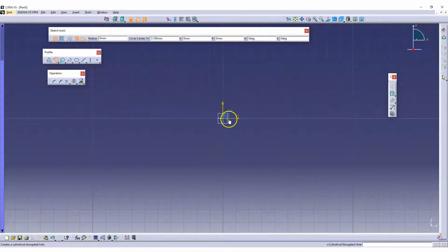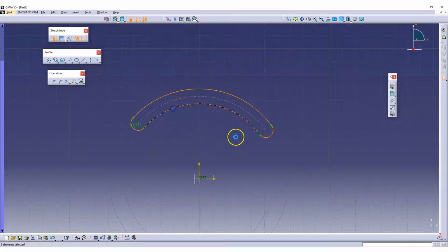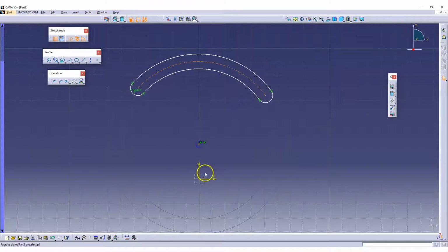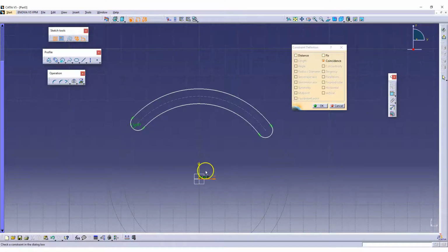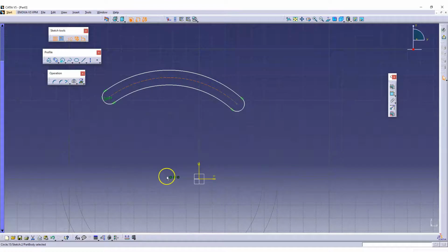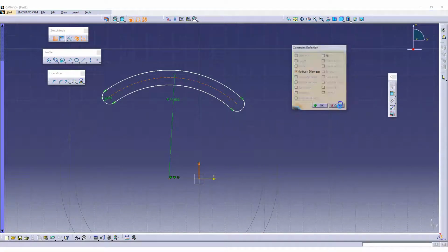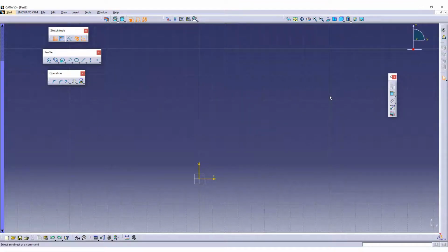I'm going to use the same thing. So just select this one and just draw the sketch. Right. So this, it's flying in space. What do you do? Make this one and this one coincident. See this? And make this point. It's flying in space. See, that means it can fly. Give OK. It's flying in space. That means it's moving there. Take this point and make this point with reference to this axis also constrained. You can do anything, right? You can fix it, whatever the dimensions you would like to do it. So constraining is so important in terms of the geometry, very important.